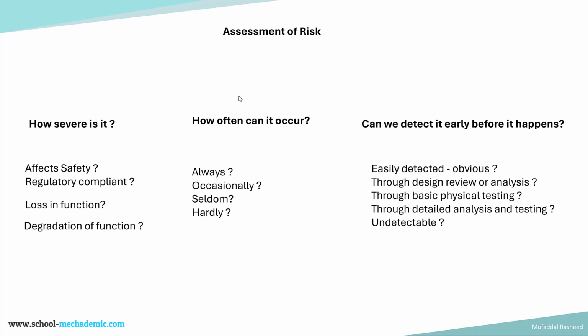The next factor is detection. How easy is it to detect that failure mode in design? Let's say, for example, you're having a design of a bracket, and by looking at the bracket itself, you can make out that the material is very thin, and just by looking at it, you can predict that it will fail. It will not take the load. So that's the easiest part of detection, that you can make out by visible inspection of the design.